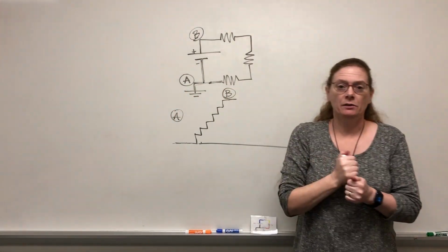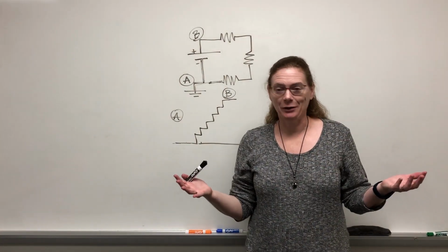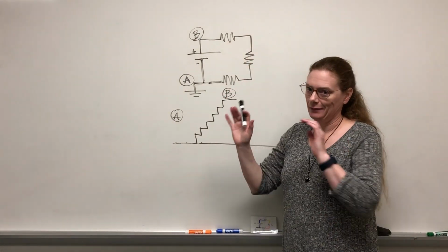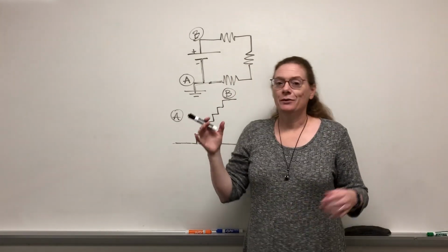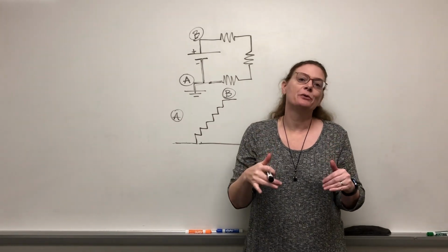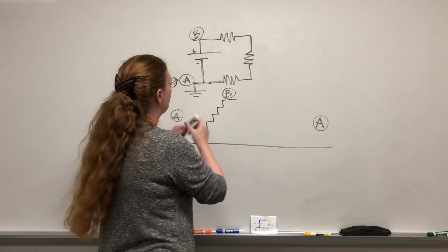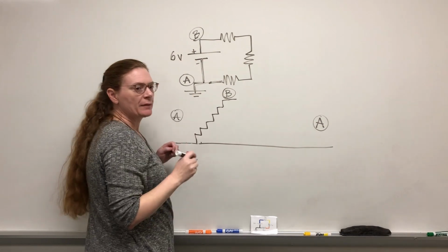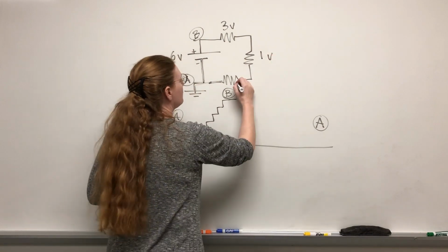Now, we have 3 resistors, and we know we have to end back at ground level. Does that mean a resistor is going to be adding energy or taking it away? There's multiple ways you can think about it. They all have the same current flowing through them, so they all have to do the same thing, add energy or decrease. Your intuition is good here too. The resistors remove energy from the circuit, so they decrease the potential. They're decreasing the voltage across 2 points in the circuit. So if I have point B, I'm 6 steps up. Let's say that's a 6-volt battery.